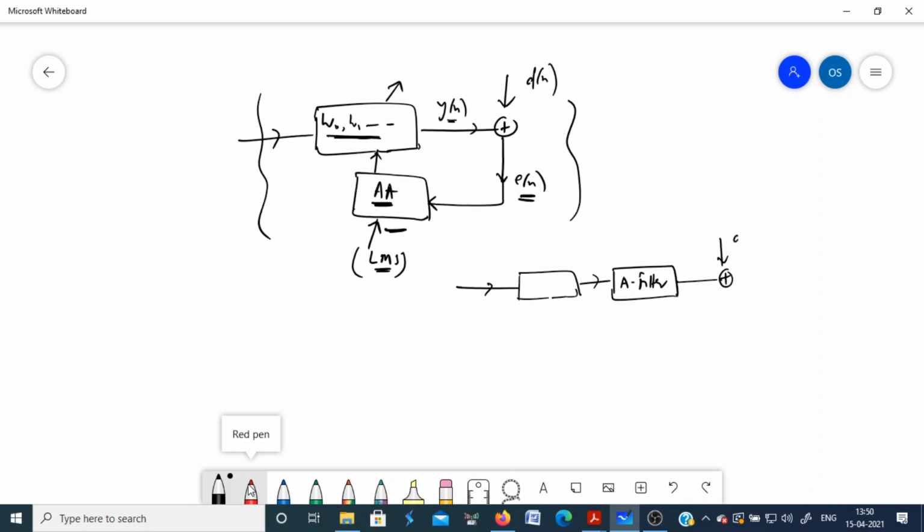And now this dn sequence is basically what is given to your channel. We have seen how you generate this. So you have a pseudo random generator, and the design at the transmitter and the receiver is the same, so that these two sequences are exact replicas of each other, or you can say what the transmitter is transmitting is known to the receiver for the time being.